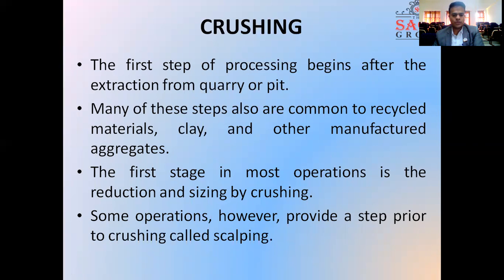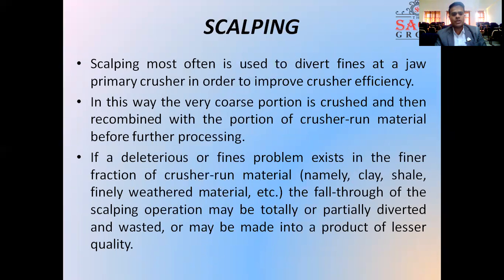Some of the operations, however, provide a step prior to the crushing called scalping. That means in the initial stage, the material which has disintegrated into small pieces, or the clay or the rocks, are initially separated out, so it is called scalping. Scalping is most often used to divert the fines at the jaw primary crusher in order to improve the crusher efficiency.